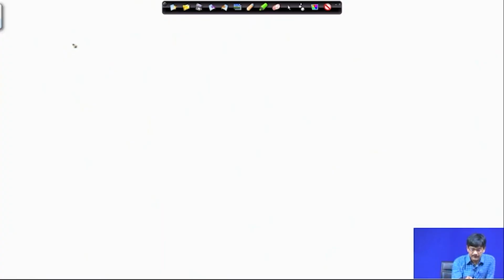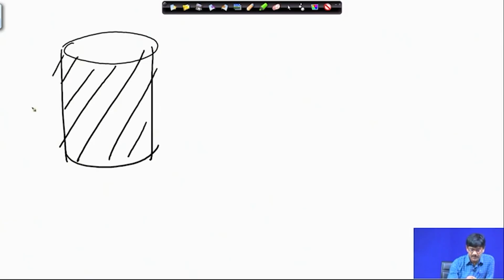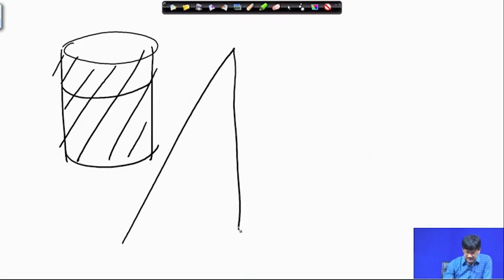First of all, if this be the gear, these are the helices. As many teeth as you have, so many helices. So, it is a multi-start threaded element, but we take only a slice of that, and this is our gear. If we unwrap a single helix, it would look like this. This is it, where if we are unwrapping it, this must be pi d.